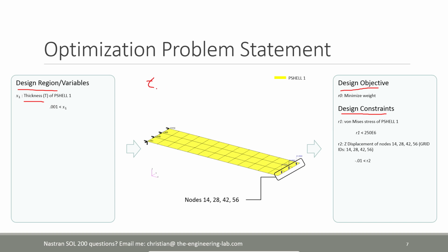So right now, we only have one thickness if you're performing size optimization. Again, with topometry optimization, from that one thickness, it's going to give each element its own thickness automatically. So T1, T2, and T3, and then here we're going to have T4. It's going to vary each thickness on an element by element basis.